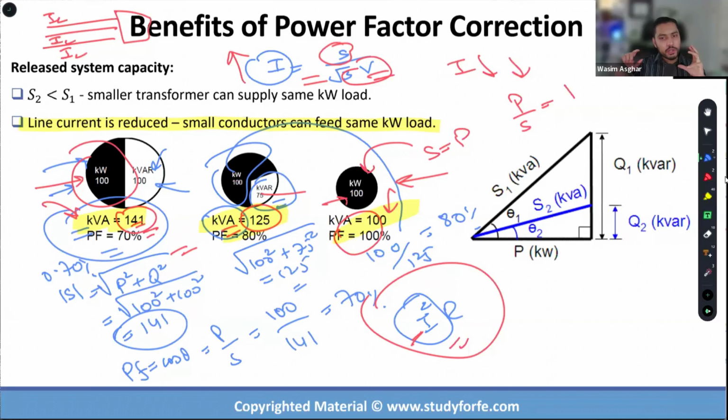So the actual real-time dynamic power factor correction management, especially at utility level, higher medium voltage levels, is a very specialized field in itself, and there are multiple ways to do it. You can have a synchronous condenser in the form of a motor that has an overexcited field. You can have static VAR compensators and so on and so forth. So that is a whole different ball game altogether.